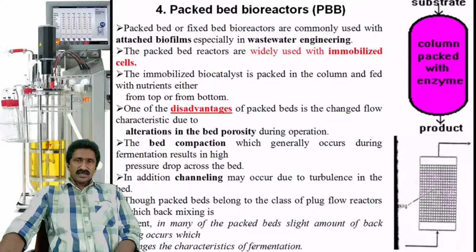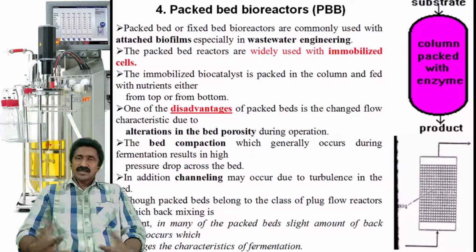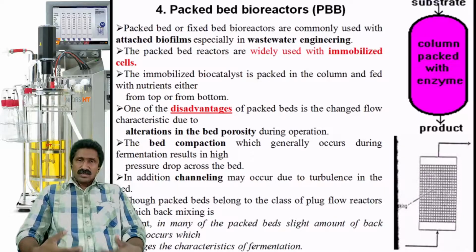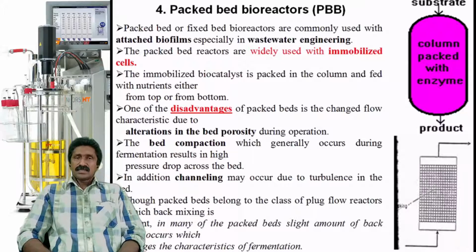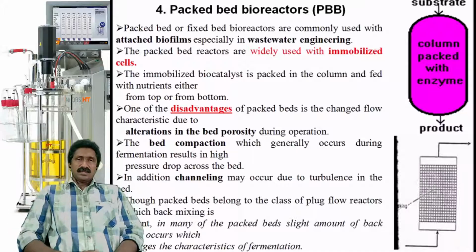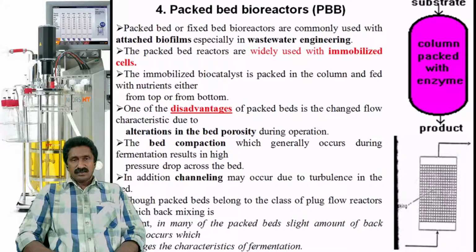That channeling effect will reduce the efficiency of this type of reactor. If it is not properly maintained, there is a chance of altering the bed porosity and creating channels, so that uniform flow through the reactor will not be there, and that is one disadvantage.